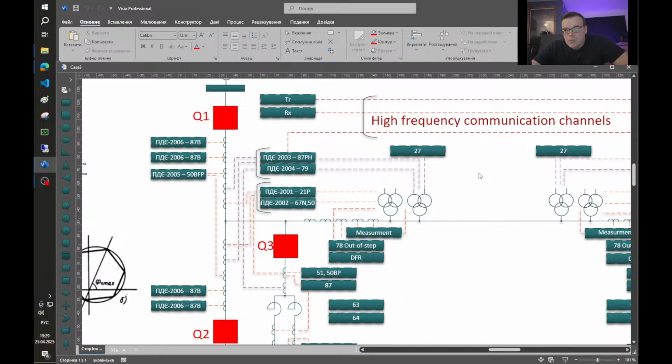And the main problem with single phase is that during this pause, the arc can be difficult to extinguish, because the healthy phases that are in work, through the mutual coupling and also mutual capacitance, give life to this arc.